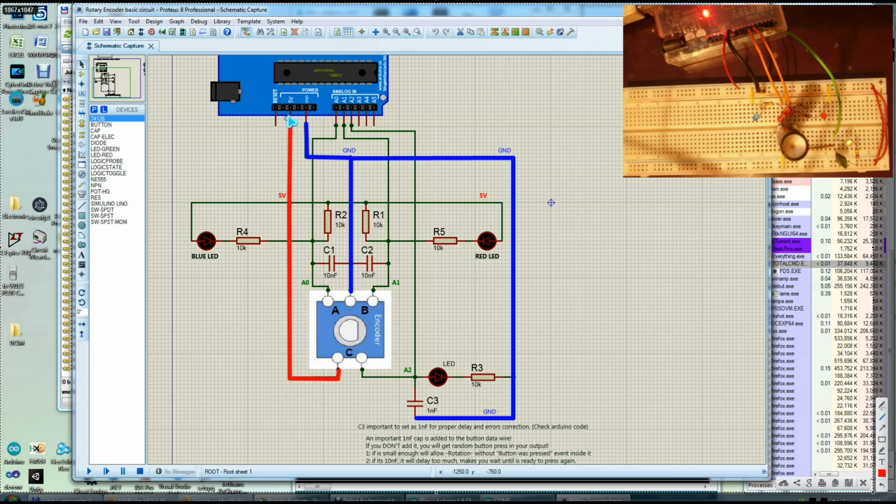When I'm pressing the button, it's putting the A2 pin to high, while it's not connecting when the button is not pressed. It is always in the low side. This here, and this one that is passing over that line, here and here, for these two LEDs. So this red and blue LED are connected to the positive with a resistor to this data line, because when I'm pressing the B button, this line will become negative. And when it's becoming negative, you see here is a node, and this LED will light up when this line will become negative. So this is A1 linked to A1 there. This is A0 linked there and here, like that.